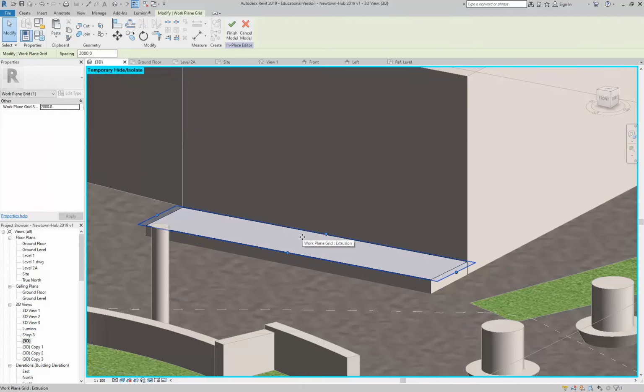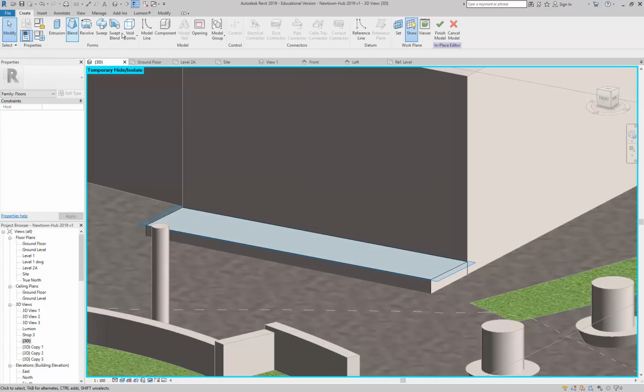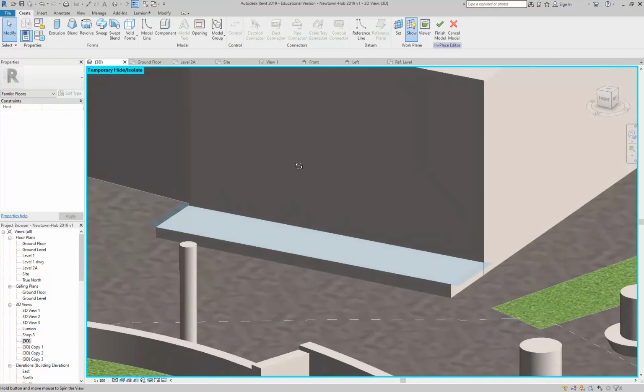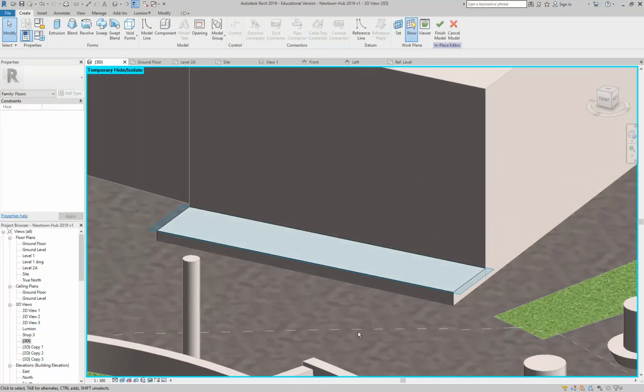So you don't always have to do that because when you're working with a sweep, you'll often be drawing in a plane that's parallel with the ground. So you don't always have to choose a plane, you can just use the ground floor plane usually, or the plane that it begins with. But here again, it doesn't hurt to see the plane, and I've got the show option on so that you can see the plane. That's a nice thing to try when you're not sure which plane has been set, just use that to find out. But I'll turn it off again now that I know, and then go and make my sweep.